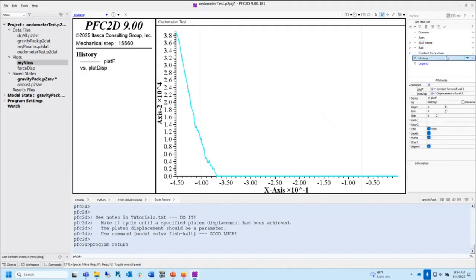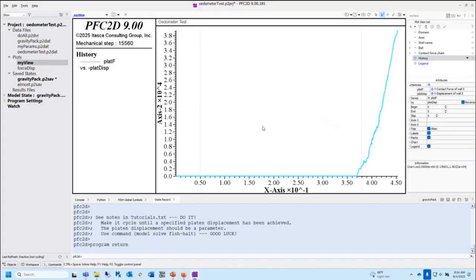So in the history plot, we can do that. Here we go, versus platen displacement, and there's a thing called reverse. If I click reverse, now we're happy. Notice here it's saying it's plotting versus the minus of what it's monitoring, right? So now we've defined in our plot the positive x-axis as actually compressing the material, moving down, okay?